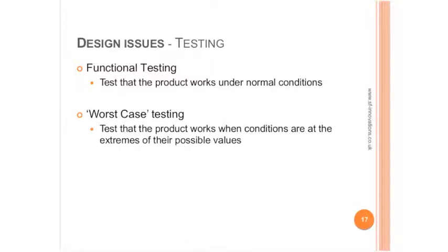So really it pays to test product works on condition of the extremes of their possible values. This could be voltage, current, or temperature. And in my view, it's best if that testing is done not by the design engineer, but by another person who can be really objective when they're doing those tests. So really, in a sense, the failure we looked at earlier, such as the caller ID telephone and the alarm telephone, both of those would have been picked up under worst-case testing if we put them in environmental chambers.